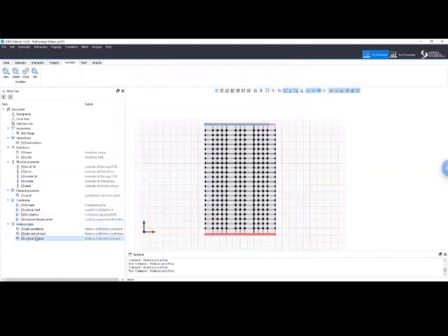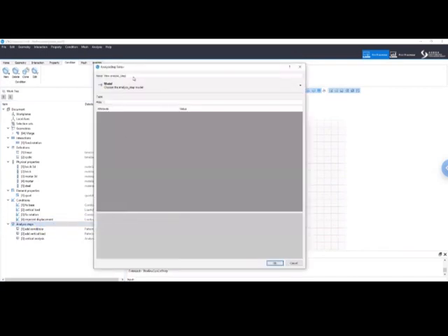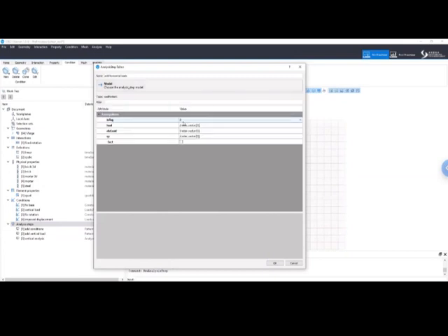Then, after the vertical analysis, we want to apply the imposed displacement for the horizontal analysis. So we go under Add, and we choose Add Horizontal Load. As before, we go under Pattern, we choose Add Pattern, and we choose Load Pattern. This time, the horizontal load is not actually a load, but it is a single point constraint.